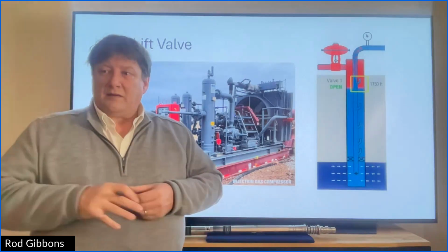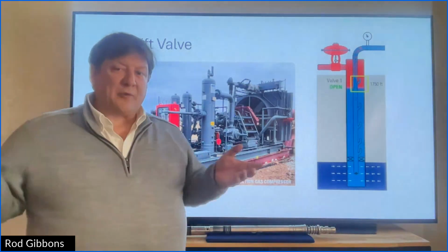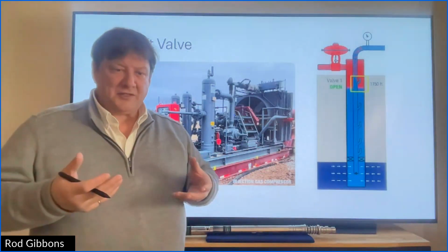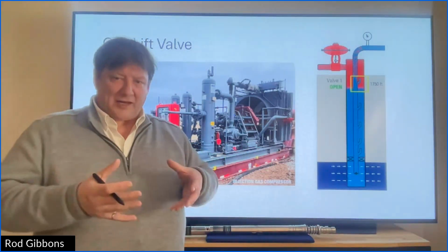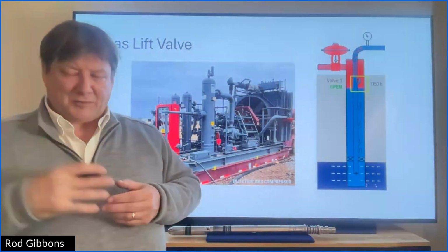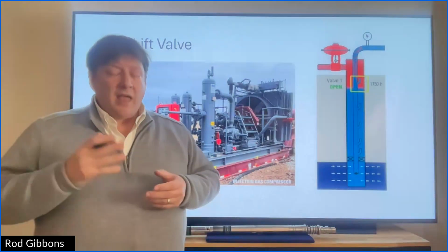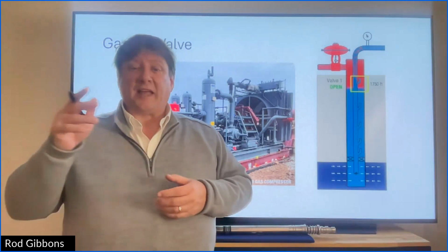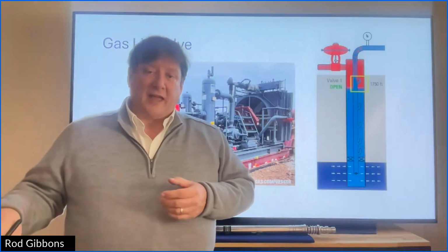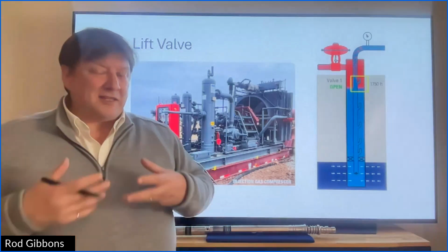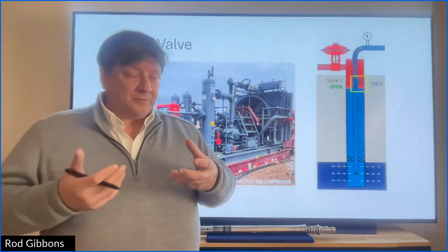So I want to sell it down a gas pipeline. Well, the gas pipelines operate at a certain pressure. So you have to compress the gas, pack it in tighter so that the pressure goes up, so that it will go down a sales pipeline. And if you happen to be in a place where there is no sales pipeline, then you probably have to re-inject the gas back into the reservoir. And that takes even more pressure.